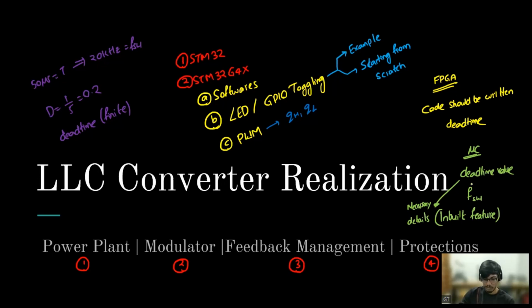But overall we have to write some. And from the STM CubeMX software, you mention all these details. When you generate the code, a majority of the code is written there, and a small initialization and the while loop have to be written. Is that clear?